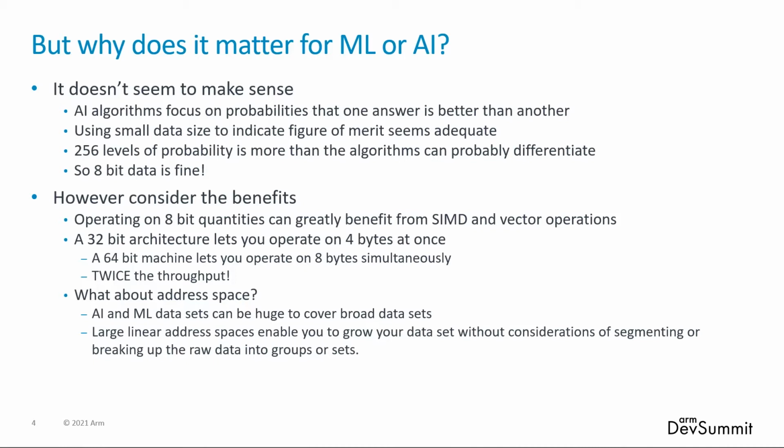However, if we look at it from a SIMD or VLIW point of view, having 64-bit registers and operations also applies to operations where many small data values can be operated on in parallel. In a 32-bit core, this generally means that you can operate on up to 4 byte values or 2 16-bit values in a single instruction cycle. In a 64-bit machine, this becomes 8 byte values at once, and likely at higher clock speeds. This can result in speedups of 2 times, 4 times, or more.